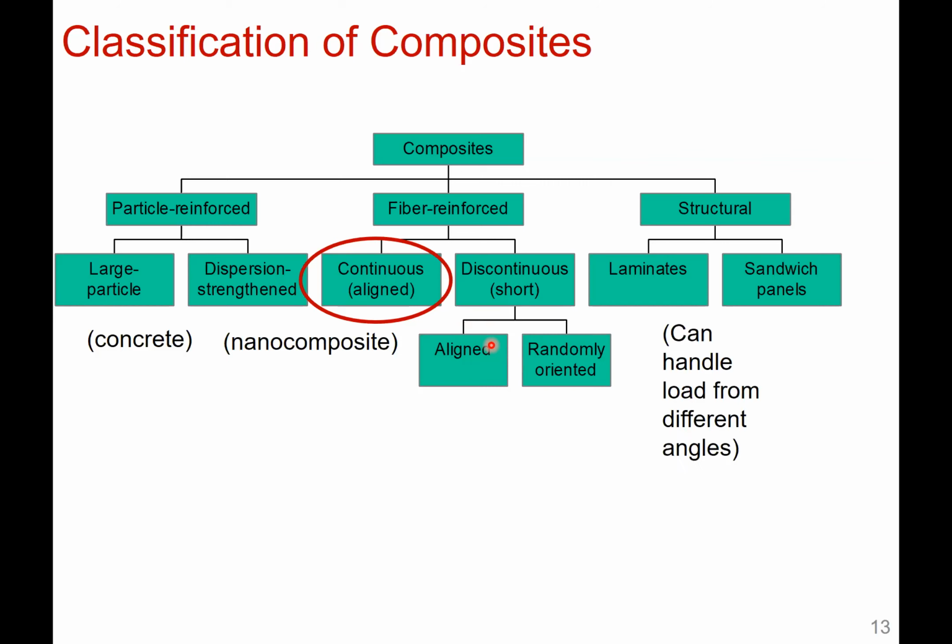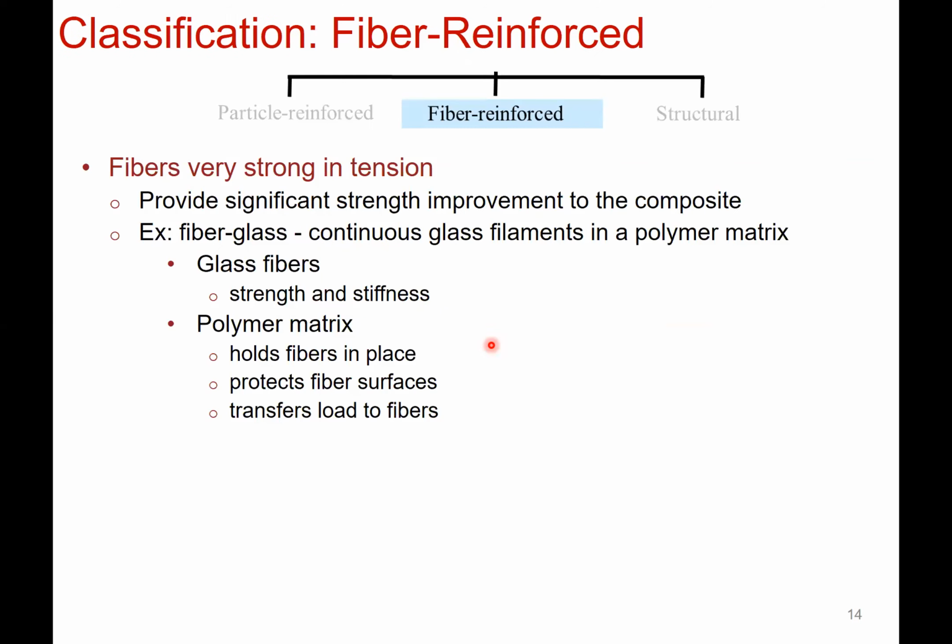Quick question, Professor. Oh, hello. Hi. A couple slides ago on the rule of mixtures, the upper and lower bound. What exactly does that mean? How does that come into play? Does that mean that the actual elastic modulus could be anywhere between those two values? Or how exactly does the upper and lower bound come into play?